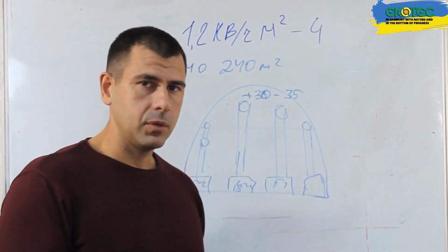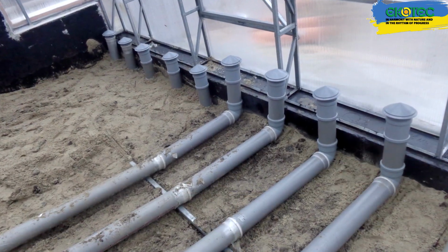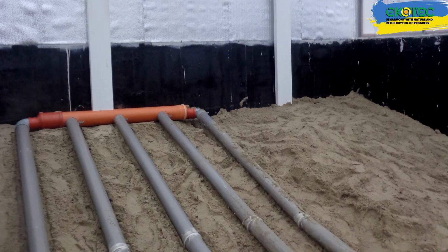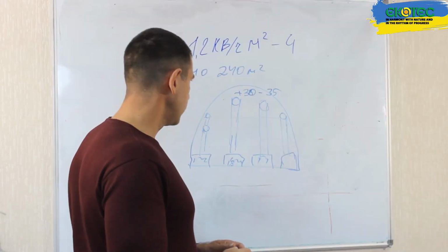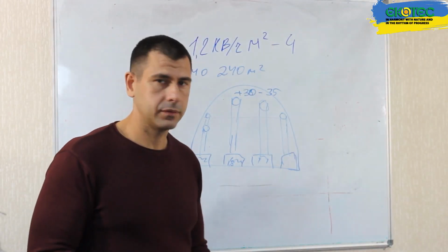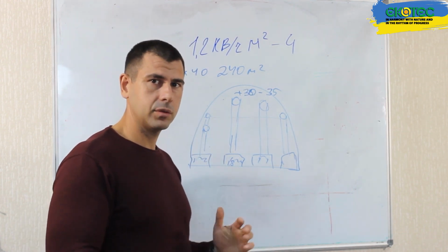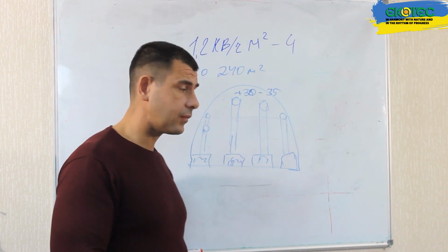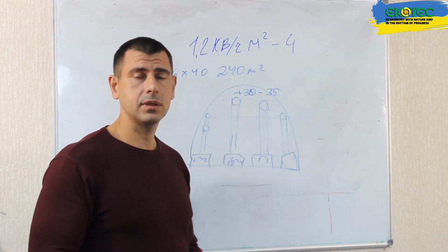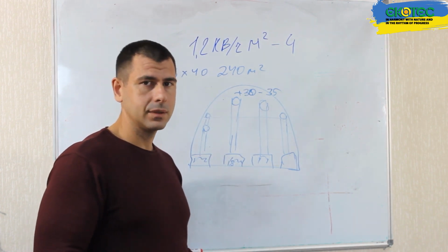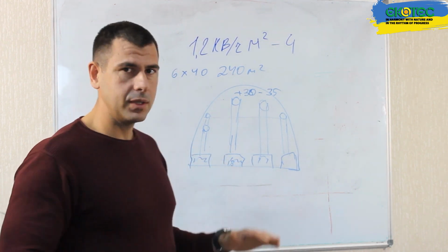When we activate the heat accumulators, fans circulate the warm air downward, where it passes through the soil and is stored. Let's do some calculations. For a 240 square meter greenhouse, we can store at least 240 kilowatt-hours of thermal energy per day. Assuming our soil beds are 0.5 meters high, 3.4 meters wide, and 38 meters long, we have about 64 cubic meters of soil. Considering the density of Chernozem soil, this equates to about 85 tons of soil.